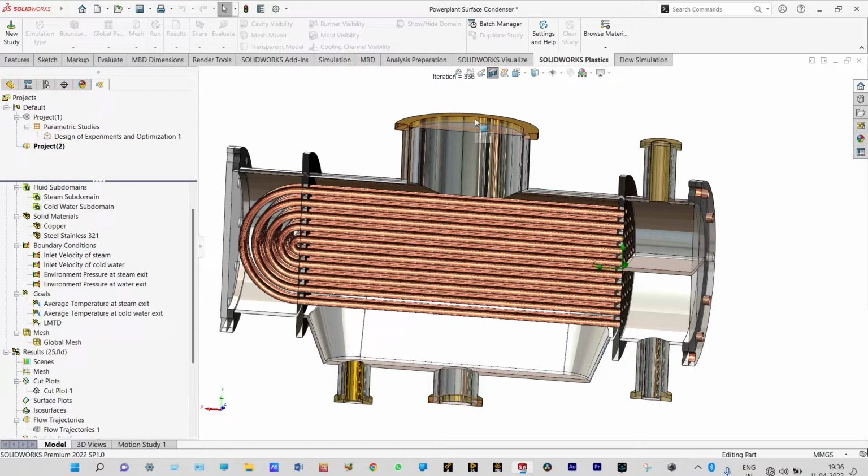And this is actually an attachment. To have a free flow of steam inside this chamber, we need to extract air from this one, and air will be extracted from this location. In this analysis, we didn't show any kind of air. We have considered that inside this one no air is there, right? So we have shown this one to show that this is the location of the pump from which we are extracting air inside. In this analysis, we will not show the existence of air, and we'll maintain zero air inside this surface condenser.